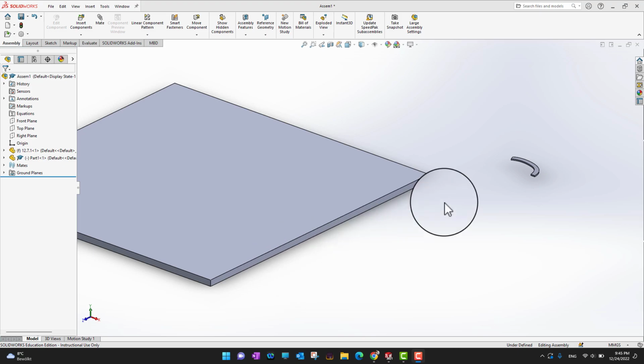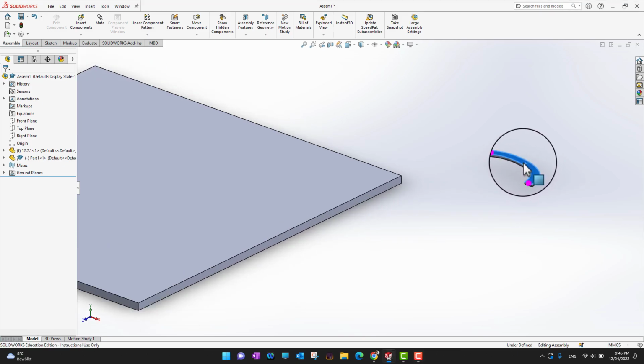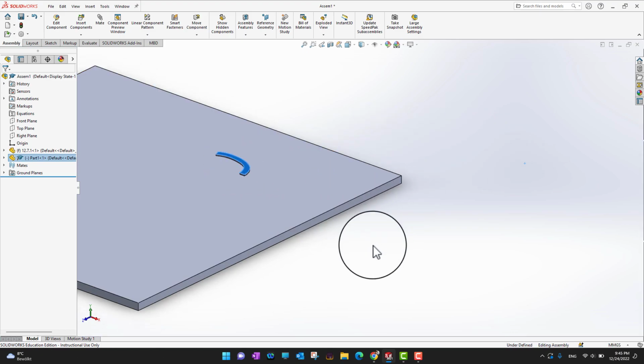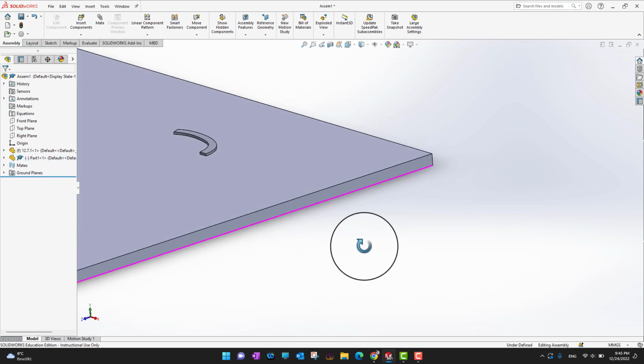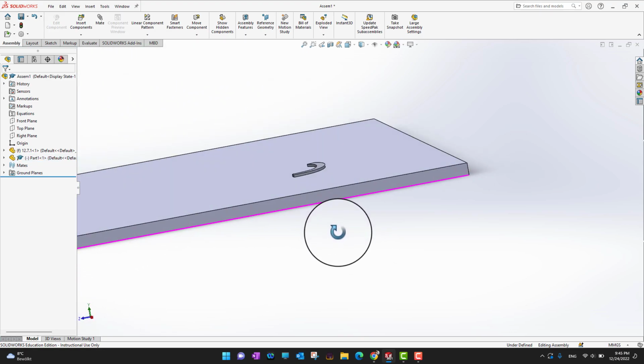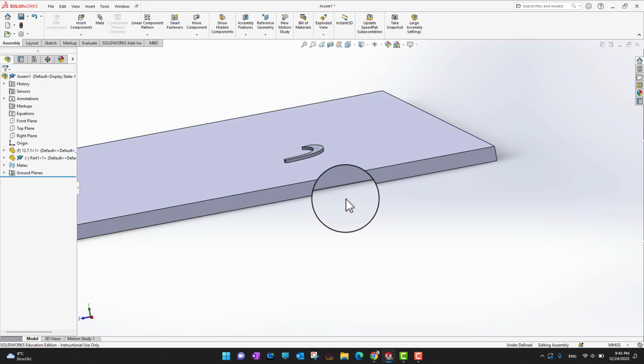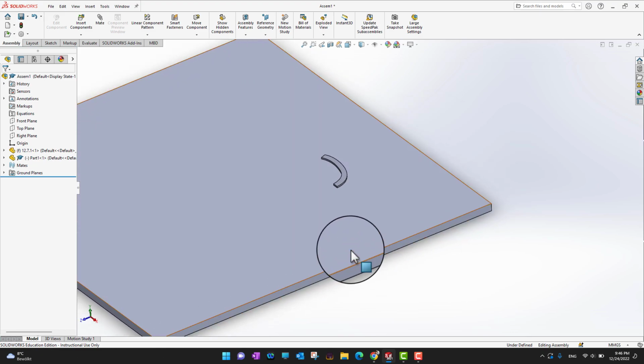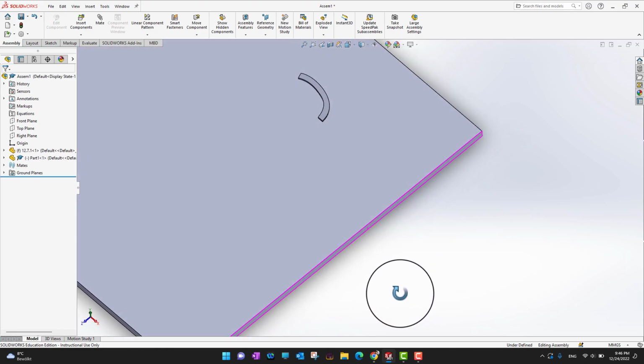Okay, after dragging the part into the assembly, I would like to drag this part onto the assembly. Whenever I am holding this part, you can see the pinkish connecting points are already activated. So I can bring it to the assembly and put it somewhere on the assembly, but you can see as soon as I put it onto the assembly, it sticks on the top surface, because there was already a connection, which was the ground plane, for both of the parts.